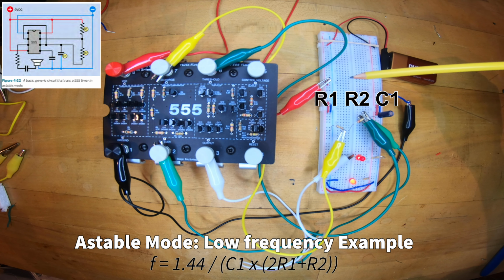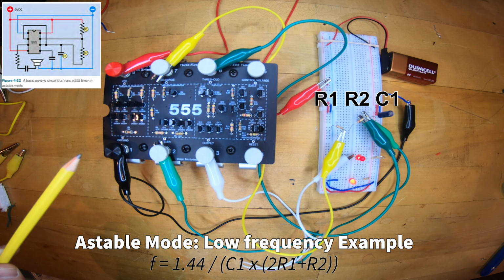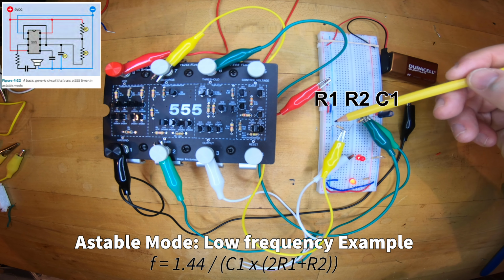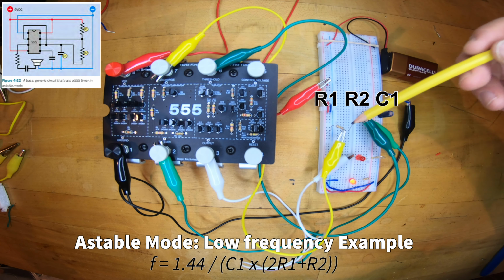So in a low frequency example, I've adjusted R1, R2, and C1. I've got power hooked up to my IC, to the rails, a 9-volt battery. I have coming from R1 on the yellow cable going to the discharge, so that will drain the RC circuit when it's time to flip.